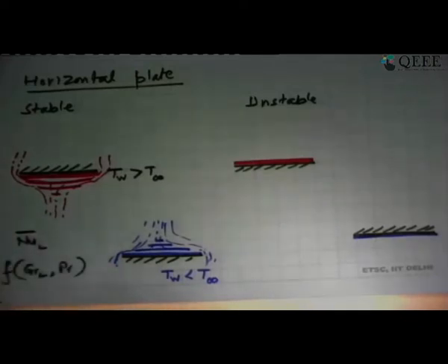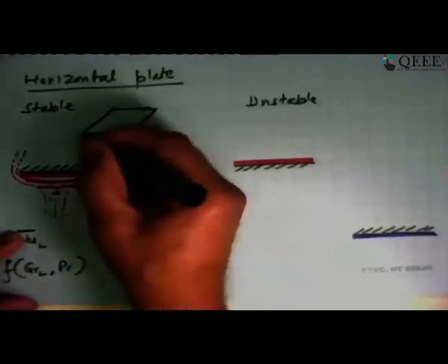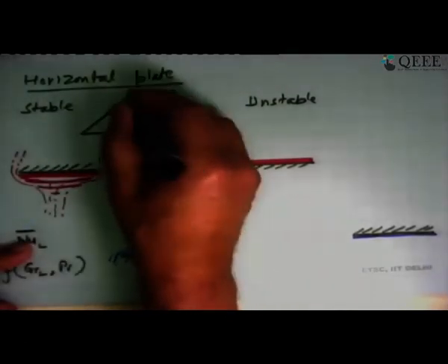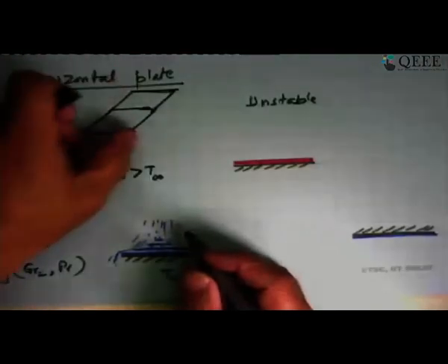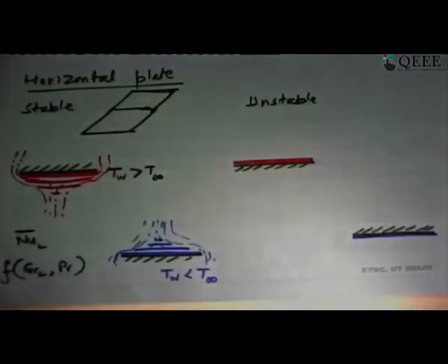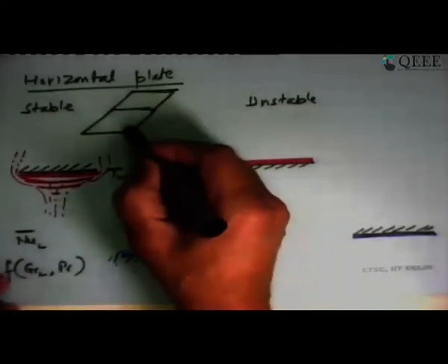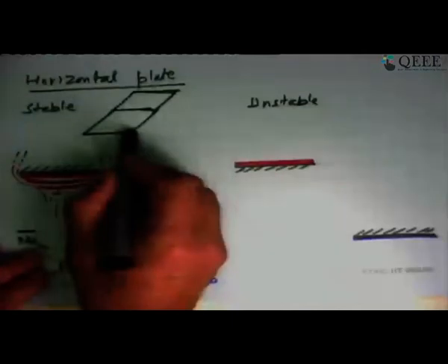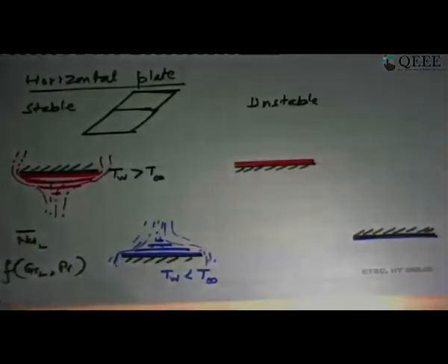But it could so happen in real problems that normal to the surface, nothing is infinite. So you could actually have a plate that is square, then at least you know that both sides are the same. If this thing is circular, you know that the diameter is there. So well, what will you do if the plate is rectangular? One side is much bigger than the other side. So then you have to worry about whether I use this parameter or I use this parameter. If this one is much longer, then only this one will dominate the heat transfer coefficient, otherwise the other one will come into play. So all of what we do would mean that we are working with an approximation.